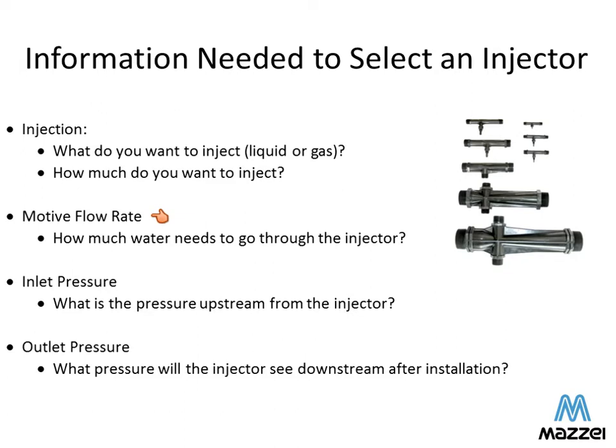Just to reiterate, the injector does require a certain flow rate at a certain pressure. So it is important that whichever injector is chosen, the amount of water available in the system is greater than or equal to the amount of water that the injector requires. So you don't want an injector that needs more water than you've got available to give.